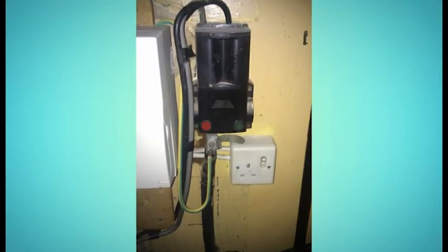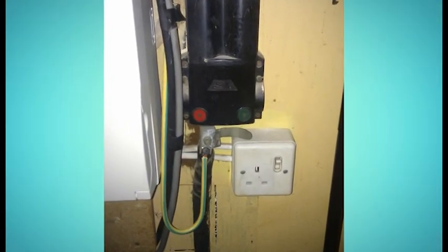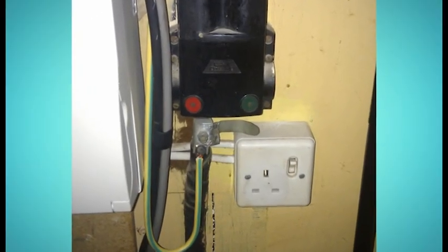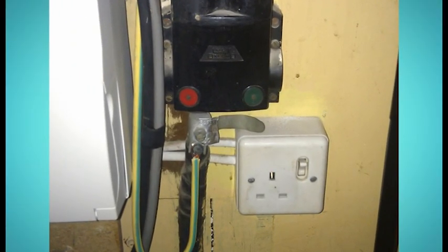But one defect you may find on older TNS installations is that a BS951 clamp has been used as a means of earthing. This is probably because there was no previous means of earthing provided by the distributors. BS951 clamps are not designed to be connected to the armouring or lead sheathing of a cable and are an unreasonable means of connecting to the distributor's means of earthing.